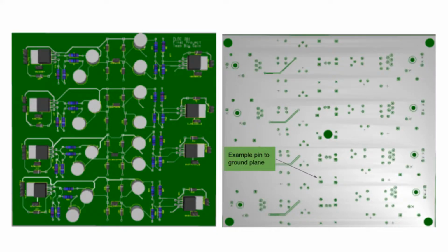First, we look at the PCB. It was made with a minimum amount of vias. We used M3 holes for mounting the board to the housing. The ground pins are easily visible on the bottom copper layer of the circuit, and it has a compact design that resembles multi-sim circuits for better debugging.